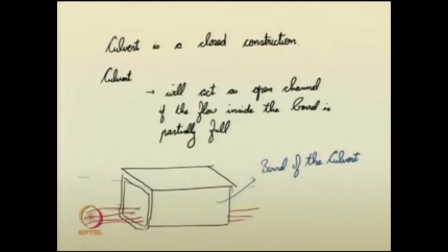If it is partially full, if the flow depth is only filling this partly, only up to this height, and the flow is being maintained in the culvert, which is the case in many of the culverts. If you design many of the culverts, that is the better situation we require. Such flows are open channel flows, and you can use the open channel mechanisms to understand the culvert.